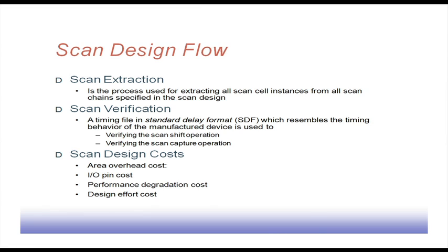Then the performance degradation cost. Performance gets degraded because some extra circuitry has been added. That may come into the critical path of the design, so delay will increase. And then design effort cost. That is the extra amount of man hours and effort that needs to be put in, so that this scan insertion is done properly and testing can be carried out. So that is another issue.